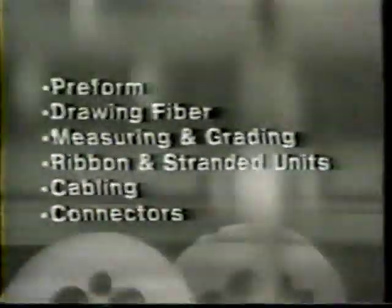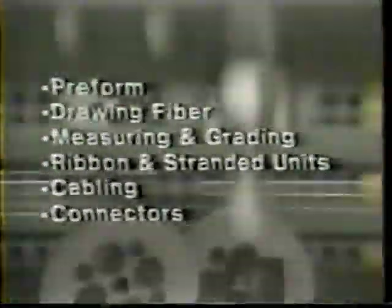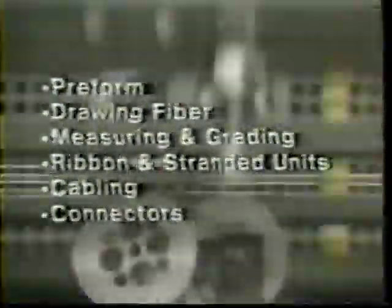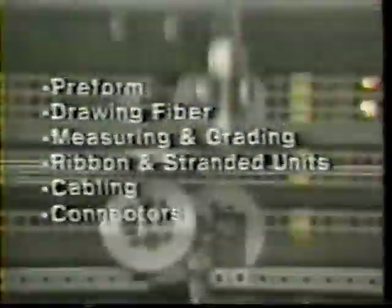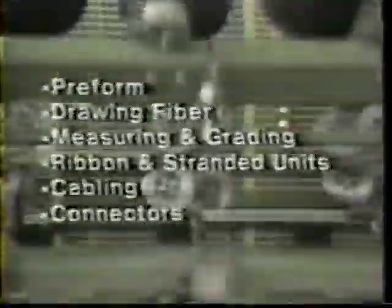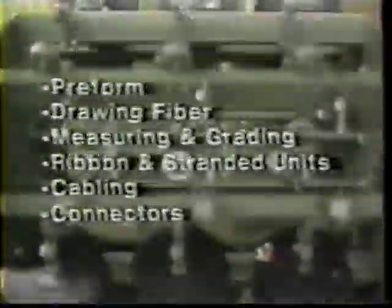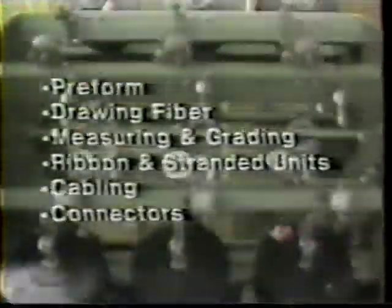Basically, manufacturing light guide cable consists of 6 processes. Producing an initial preform, which is a large glass rod with good optical properties. Heating this preform and then drawing fiber from it, similar to pulling taffy. Measuring and grading the fiber to determine its physical and optical properties. Assembling the fiber into units, either ribbons or stranded. Cabling the units with a variety of protective materials. And finally, installing any appropriate connectors to the cable ends.